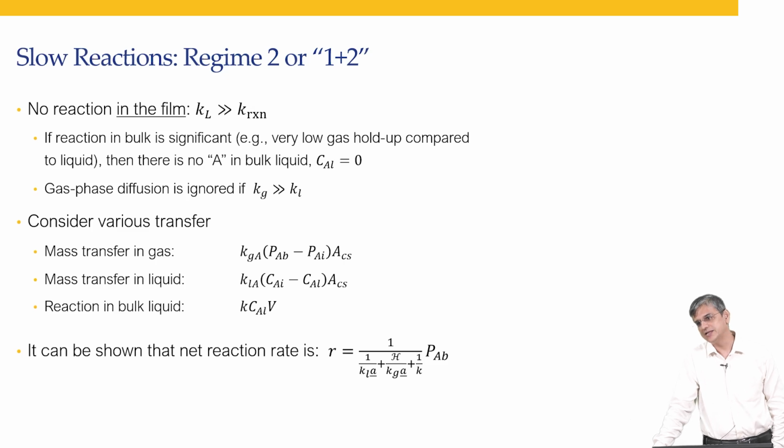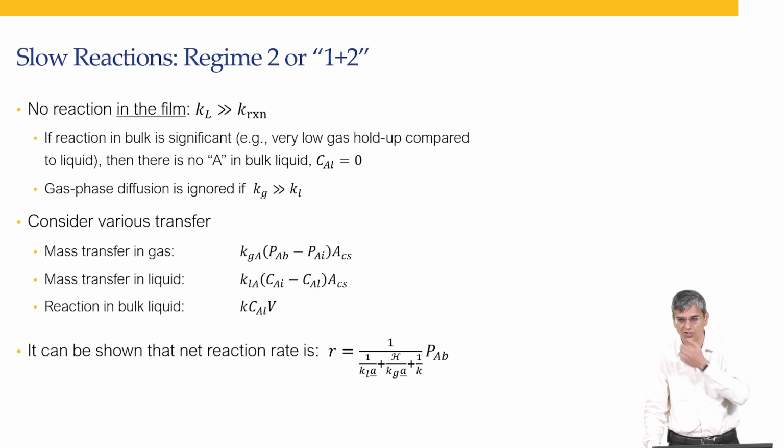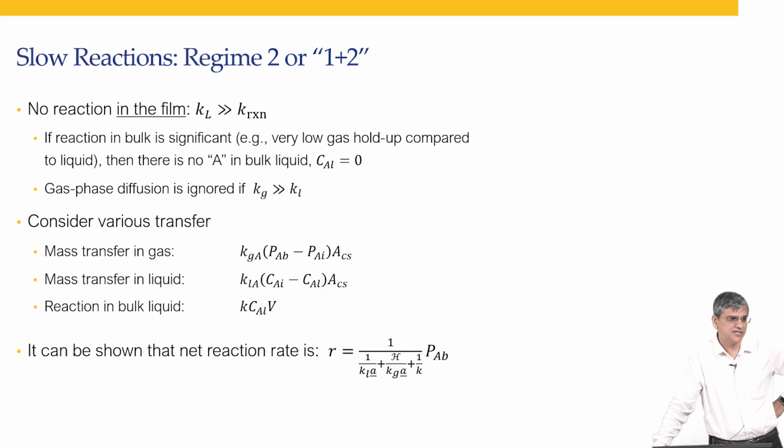Well, there is, but that is where the reaction takes place only on the solid surface, but then there is no internal diffusion at all. So, it is not exactly the same. Otherwise regime 1 is equivalent to external mass transfer limitation, regime 2 is equivalent to external mass transfer limitation and the reaction is taking place in the bulk liquid. Regime 3 is equivalent to external and internal mass transfer limitation. Regime 4 is unique to gas liquid systems. So, that is the relationship between module 5 and module 7.